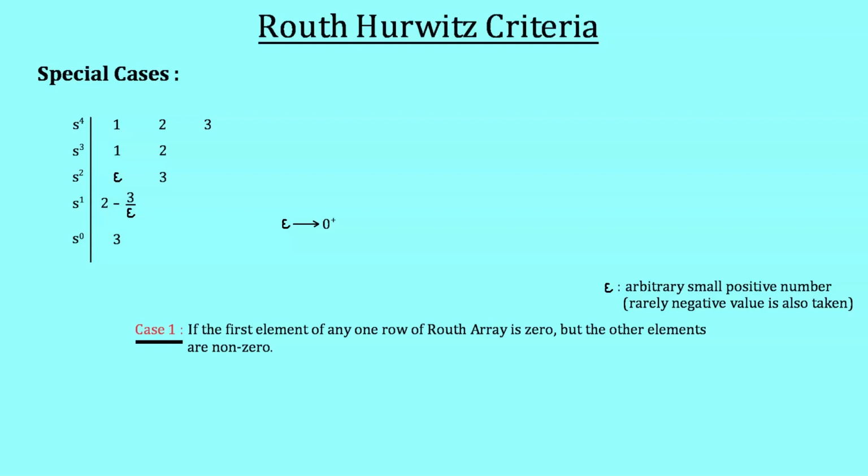Now we have the complete Routh table, which has a few elements in terms of epsilon. Our next step is to find the limiting values of all the elements in the first column which have epsilon in them. We are actually more interested in the sign of the value rather than the exact value. The element in the third row is positive, as we have already assumed the value of epsilon to be a positive quantity. In the fourth row, however, you have to be a little bit careful.